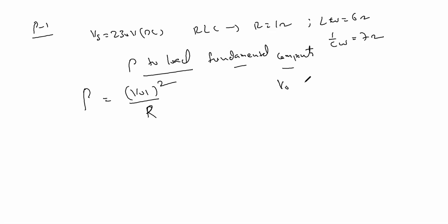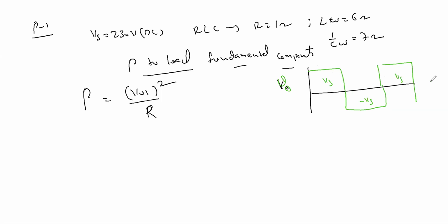How do you obtain the voltage here now? Output voltage V0, we get an alternating waveform. So this is Vs, minus Vs and Vs. Okay? Fundamental. इसमें the harmonics है. I told you already how to get this one. Fundamental means, you remember the harmonic one, 4Vs by n pi, right? So that one I have to take here now. What is that value here now?